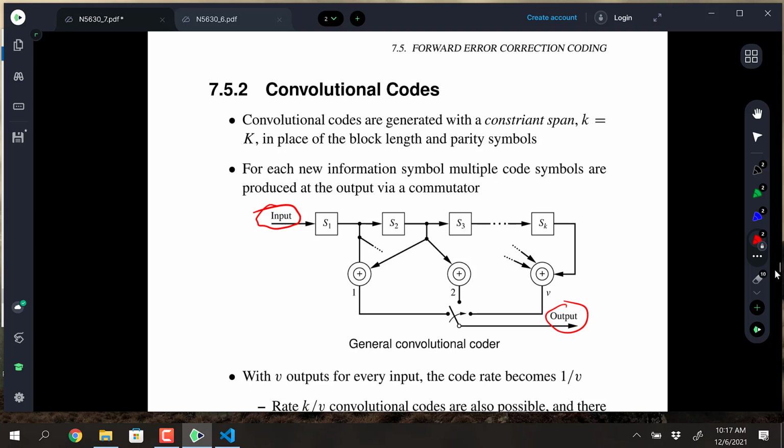And it's called a convolutional code because it kind of resembles the convolution operation when you have an FIR filter in digital signal processing. You have an input signal stream, and then you have taps with coefficients for the FIR filter, and then you form the output. So it's a convolution-like operation, only now it's going to be in Galois field, or GF2, binary arithmetic. Polynomial multiplication is what this operation is doing. And that's a whole other aspect of coding theory we just haven't talked about, all the polynomial representations that go along with both block codes and convolutional codes. So we're just keeping it simple.